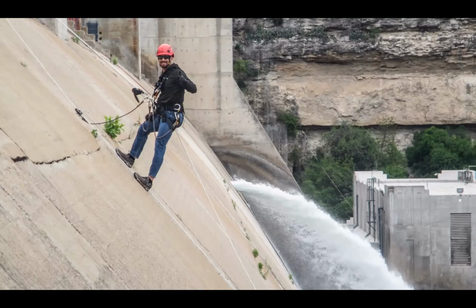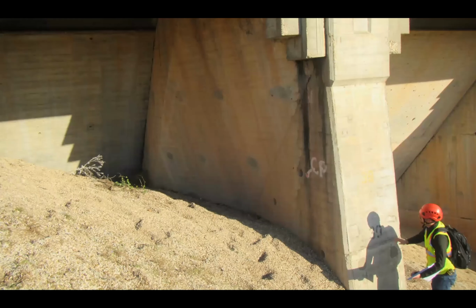After the spillway, looking at the buttresses. So you can look at the size of the buttresses here. This is compared to a person. Actually quite large. I mentioned before this dam actually is hollow. So you're seeing the exposed buttresses in this particular case. There's actually more to be seen inside the dam. And so you're looking for the same type of conditions: cracking, spalling, deterioration, corrosion of reinforcing steel, any type of compromised structural support for the different elements.